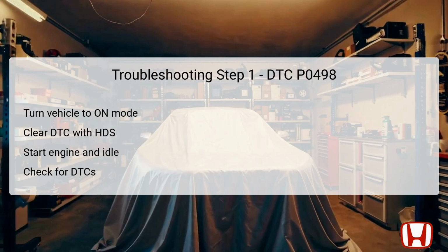The first step in troubleshooting DTC P0498 involves vehicle power management and diagnostic system initialization. Begin by turning the vehicle to on mode. It will power the onboard systems without starting the engine. Subsequently, use the Honda Diagnostic System, HDS, to clear any existing DTCs.